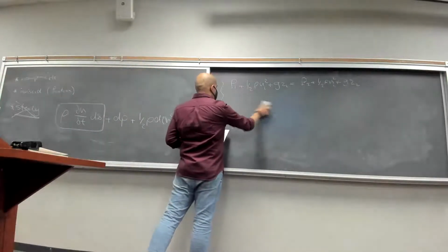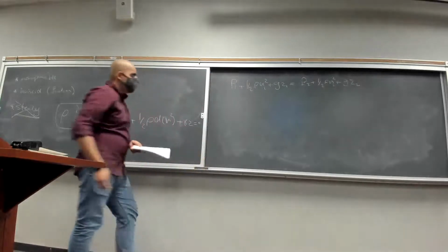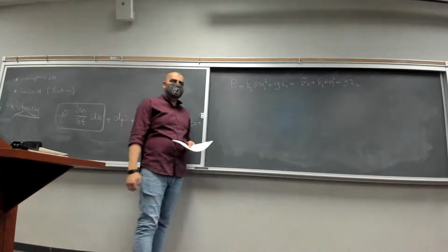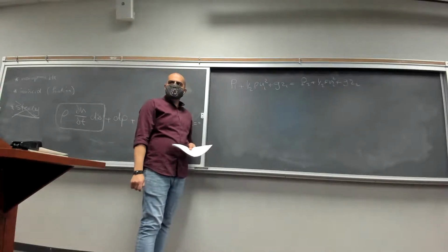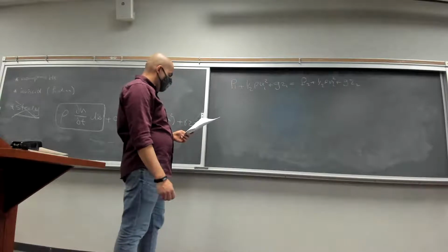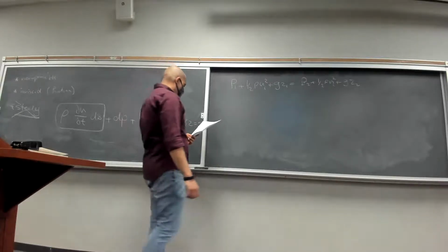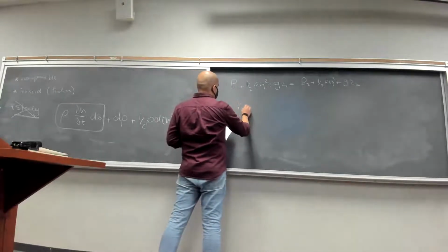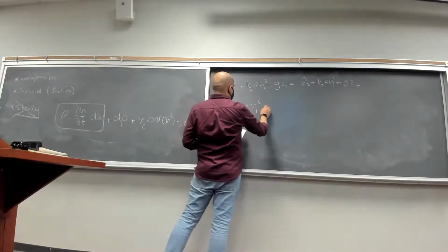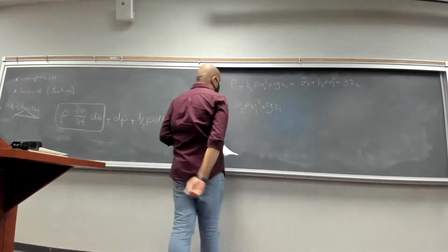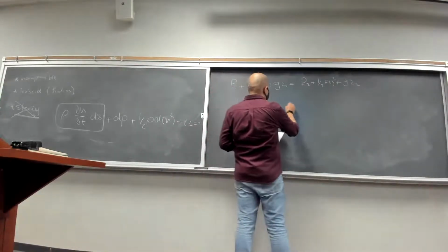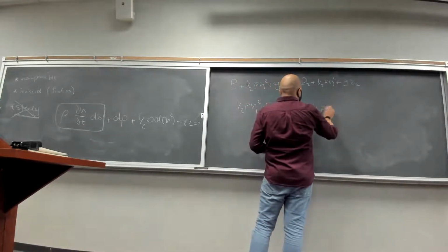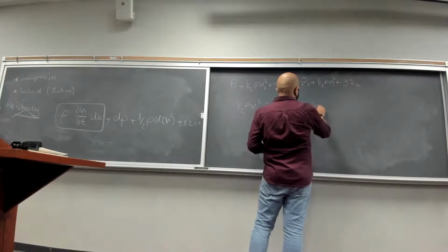Let's solve the problem. Do you have any volunteers to come to the board? Okay. No one? That's all right. So the idea is P1 and V2 are 0. We can rewrite this main equation as 1/2 rho V1 squared equals P2 plus 1/2 rho V2 squared, this part is 0, right? Plus g Z2.